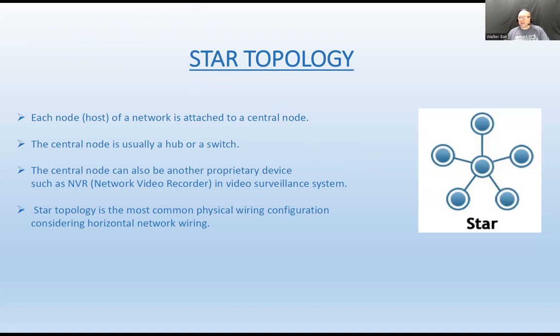Well, sometimes it is, but the only thing is that when you get those small systems with the security cameras, if you plug them straight into the NVR or DVR, if you can do that, then you don't have to do as much setup. But if you plug those cameras into the switch, and the switch is plugged into one of the ports of the NVR, then you have to do some extra setup of assigning the IP numbers and addresses and whatnot, so the NVR knows what to look for as far as signal.